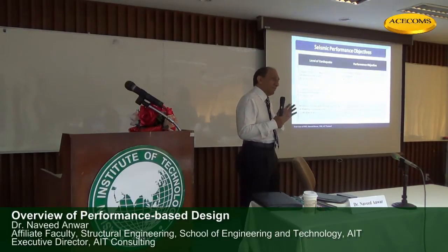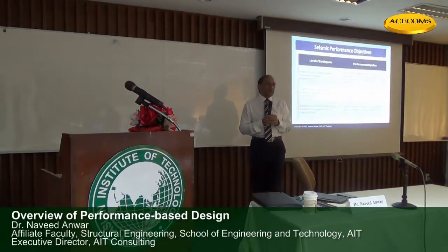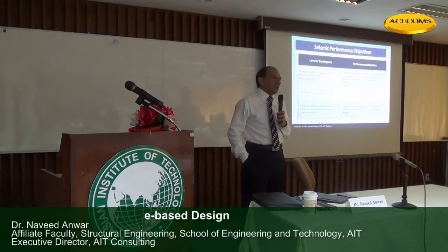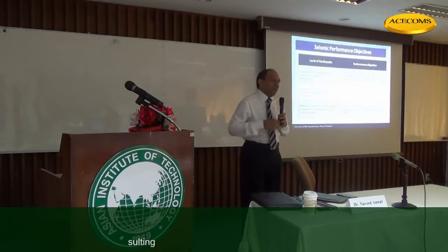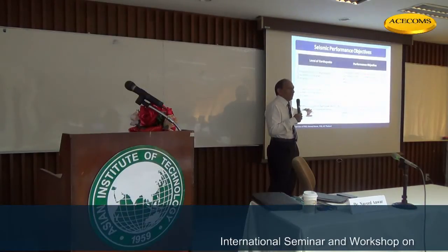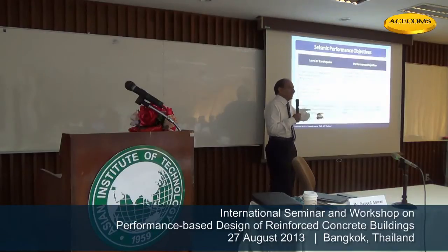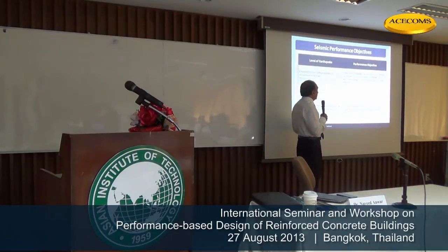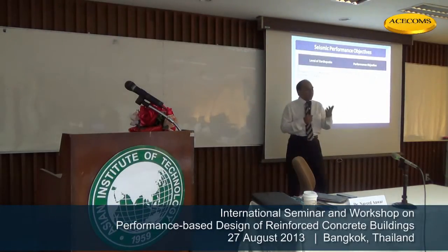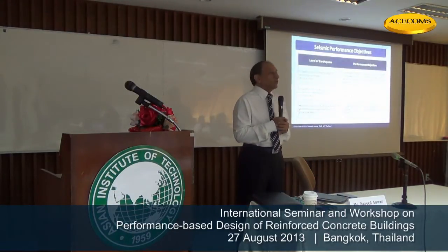Right? But some client can say, for example, the nuclear power plant in Japan, which is having trouble, is one of the examples, where you can say, no, even for this earthquake, I don't want to expect any damage. It must be serviceable, even for that earthquake. Sure, we can do that. So we simply change the performance criteria for that structure, maximum considered earthquake, serviceable. And we design for that. And we should, probably, because the consequence is too great to accept.